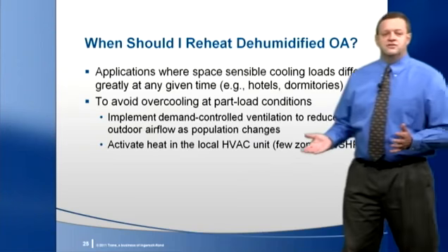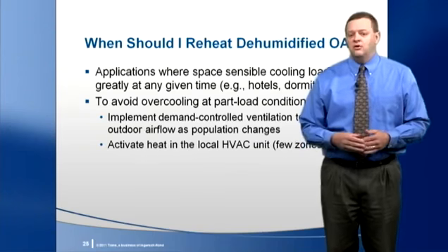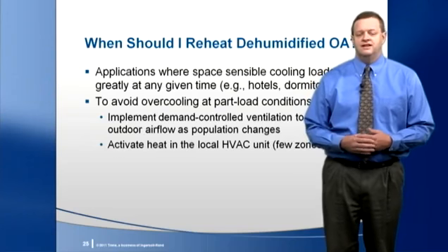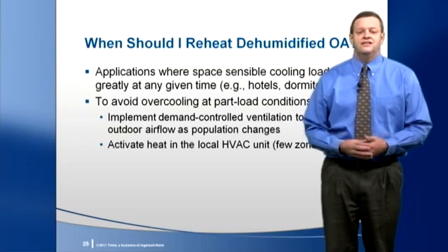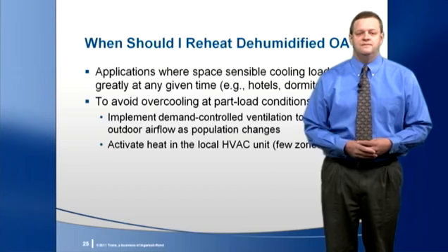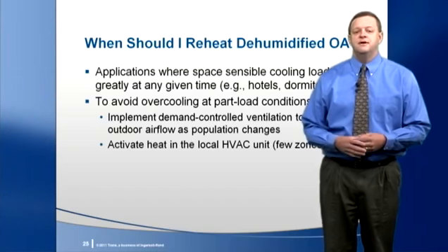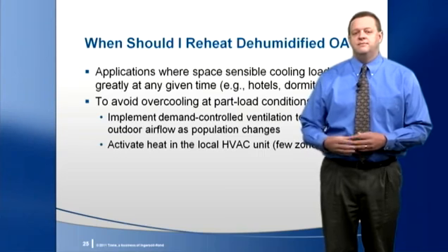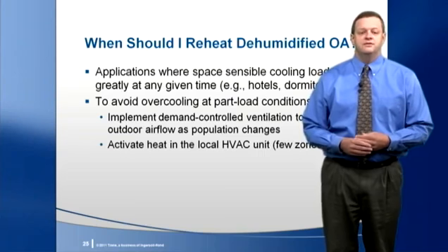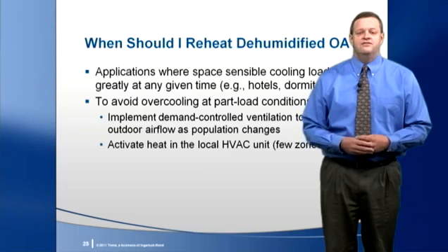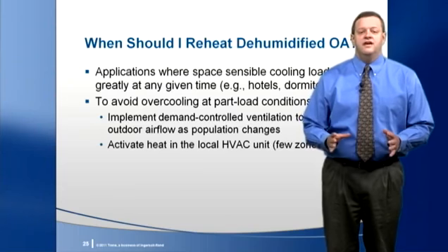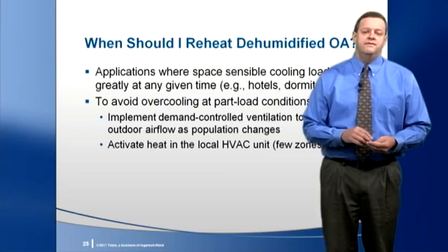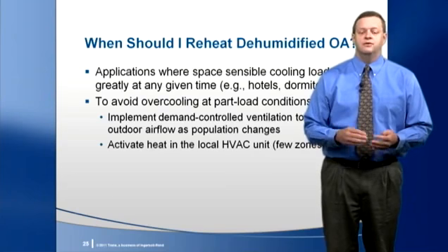Or if this is a water source heat pump system, when only a few heat pumps are operating in the heating mode to prevent overcooling by the cold ventilation air, this situation likely improves system efficiency. As the heat pumps operating in the heating mode extract heat from the water loop, they reduce the amount of heat that must be rejected by the cooling tower, saving heat rejection energy. And all the other heat pumps, those that are still operating in the cooling mode, continue to benefit from the sensible cooling provided by the cold outdoor air.